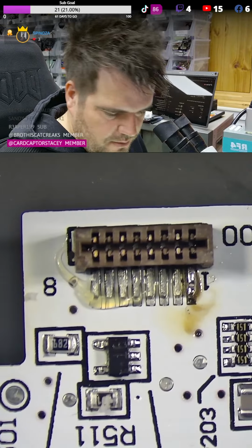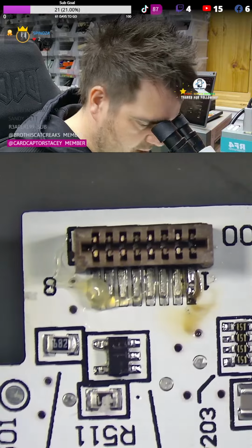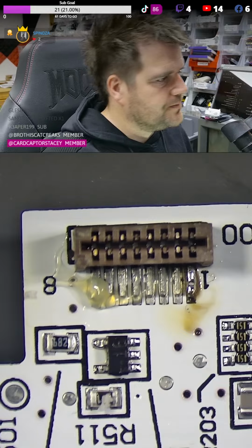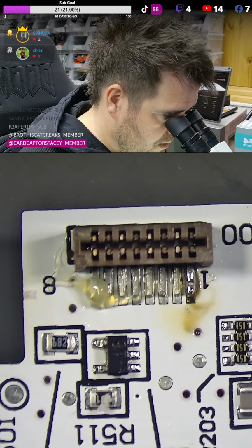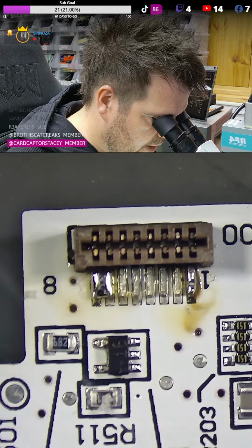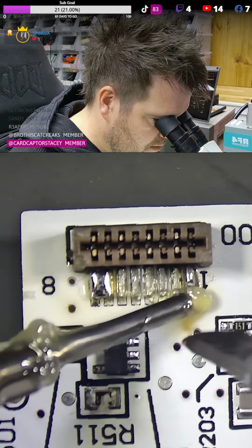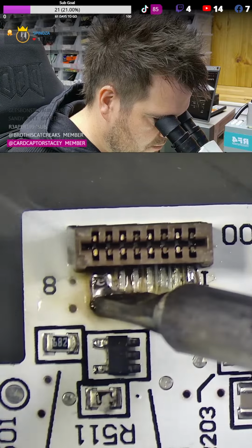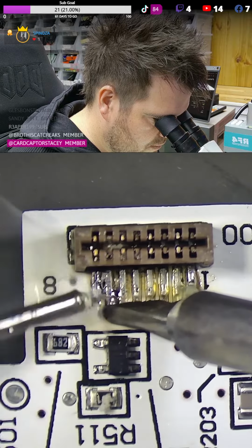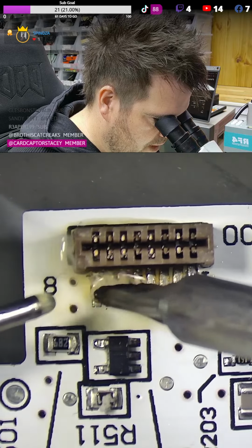And now all we need to do is, if you're doing an iron, I'll go from the other side, tack this pin in, and then I'll probably just drag solder down. So we'll go and tack one more in down here. And you can see there now what it wants to do is just bridge. That's perfectly fine. All we do is plenty of flux. Go down slowly with your iron, a lot slower than you think. And the heat will transfer through. And you'll normally just drag that off.